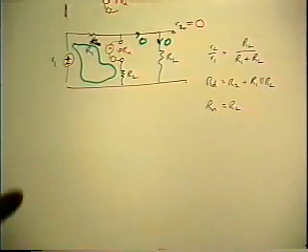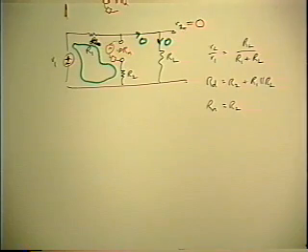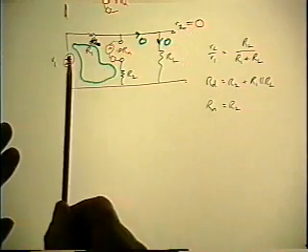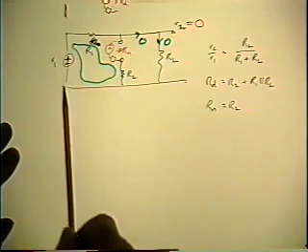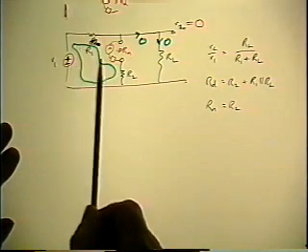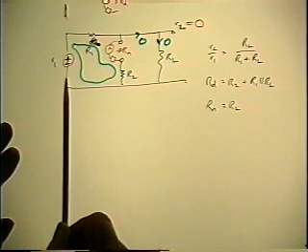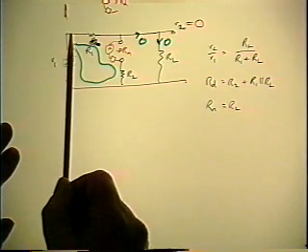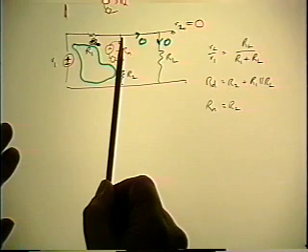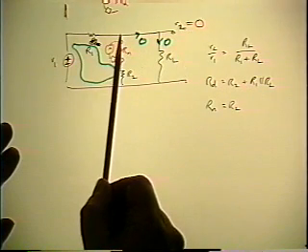In fact, the way you get the null is by adjusting these two sources, which are in series around that loop, such that the current that is drawn says that whatever voltage V1 you've stepped up to this point, you step back down to zero at that point. That's what gives you the null.